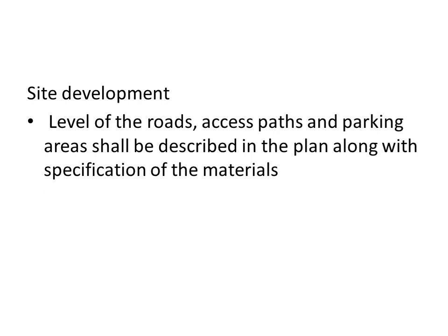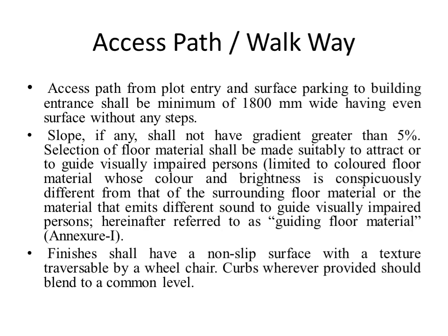Then the site development. The level of roads, access paths and parking areas shall be described in the plan along with specification of the material. Then regarding the access path and walkways. Access path from plot entry and surface parking to building entrance shall be minimum of 1800 mm wide, having even surface without any steps. Slope, if any, shall not have gradient greater than 5%.